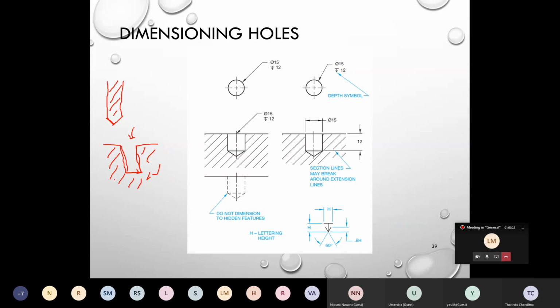So normal drilled holes have a conical bottom because you are using a conical drill bit. When you define the depth, you define up to here. This is your usable depth. This area you cannot use; it comes from your drill bit.